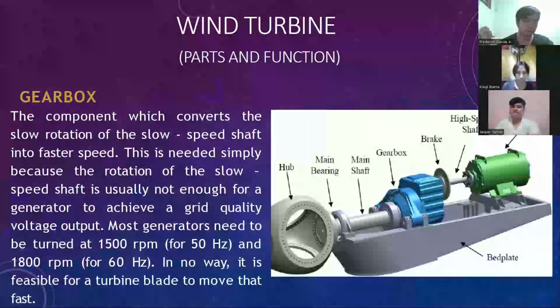So thank you. Now we see that the rotor or the wind blades actually rotate at a very slow RPM, because to reduce the imbalance, if they were to be rotating at the speed at which the generator would be operating at maximum efficiency, which is 1800 RPM for 60 hertz in our case, then they would be prematurely destroyed or worn out, requiring more maintenance.